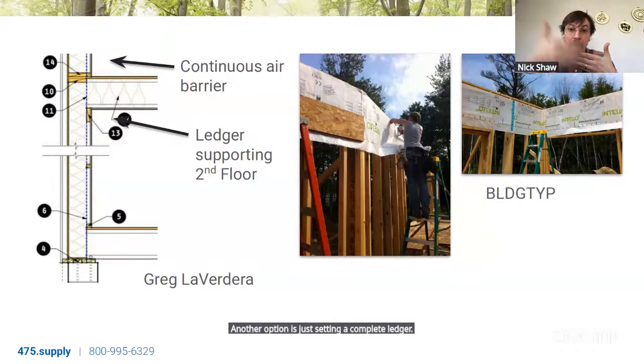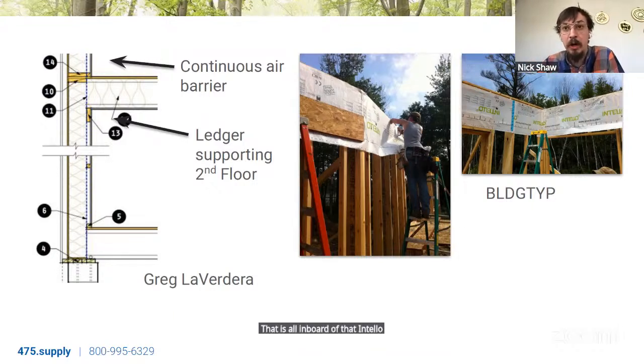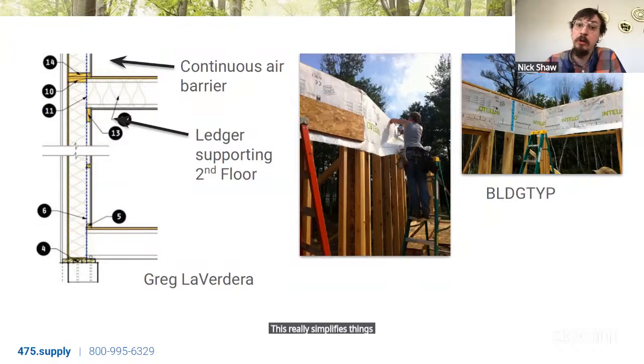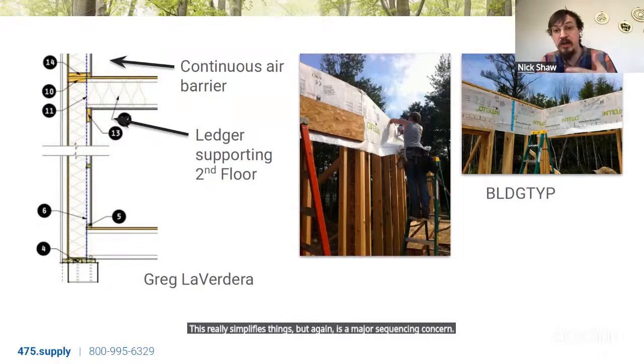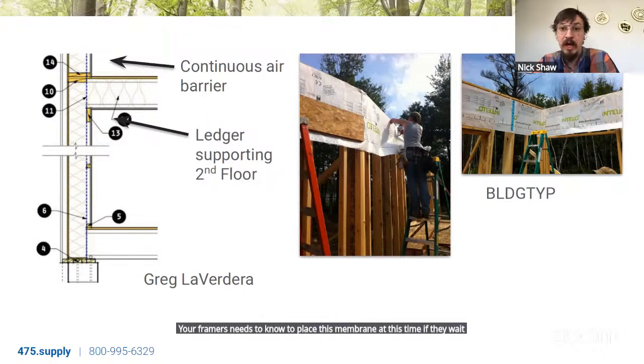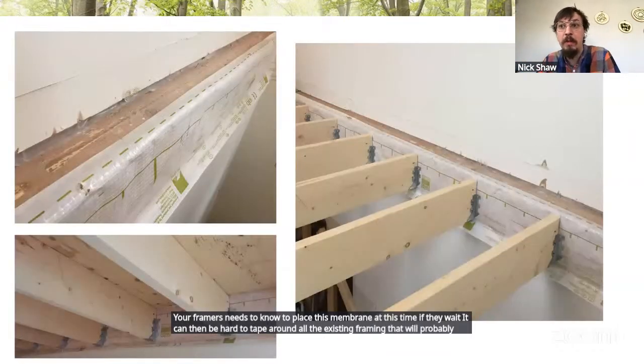So you can run that Intello membrane continuous and have a ledger board all inboard of that Intello Plus membrane, your primary air barrier. This really simplifies things, but again, is a major sequencing concern. Your framers need to know to place this membrane at this time. If they wait, it can then be hard to tape around all the existing framing that will probably be in the way and interrupt that connection.